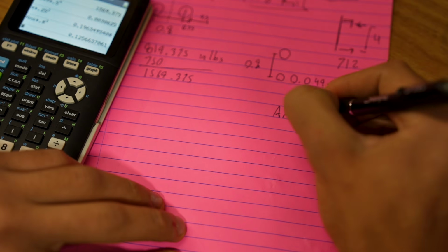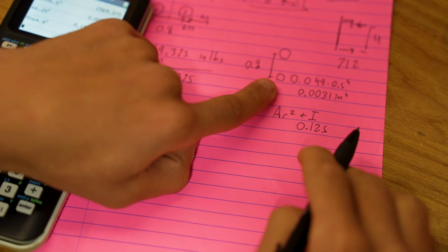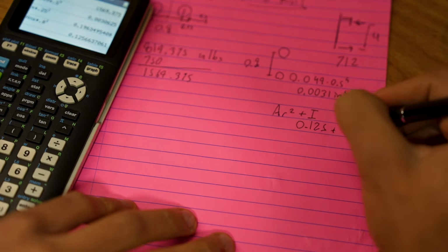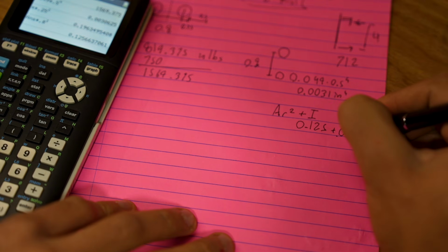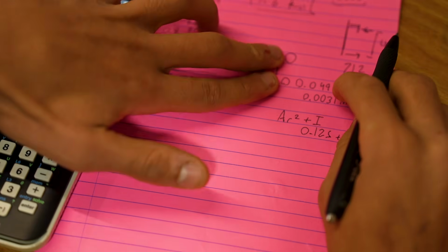And then it's actually A r squared plus your initial I. Because this also has its own bending resistance, it also resists bending on its own profile. That's a little confusing. We'll link some resources below if you want to look into calculating bending moments. You could also go into Onshape and make these two circles and select their faces if you didn't want to do this.